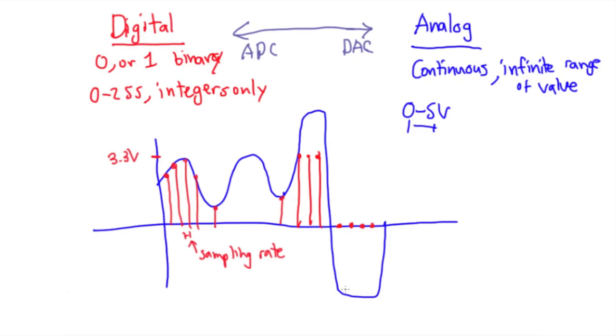So you can't read negative. It can't read negative voltages. So that's a small limitation with analog to digital conversion. On top of that, there's also the other conversion, which is the bit depth between these two ranges. The idea is that it won't be able to pick up 1.0000001 volt. It'll maybe register that as like 1 volt instead.